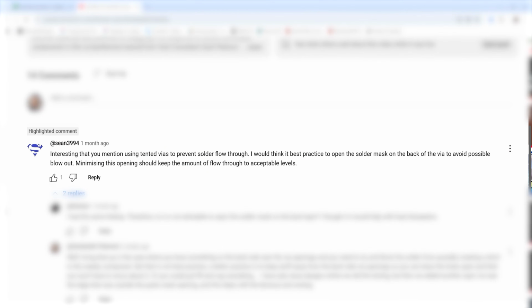This next question also comes from the bottom terminated components video, and this question comes from Sean3994. Sean writes, interesting that you mention using tented vias to prevent solder flow through to the backside of the board. I would think it is best practice to open the solder mask on the backside of the via to avoid possible blowout. Minimizing this opening should keep the amount of flow through to acceptable levels.